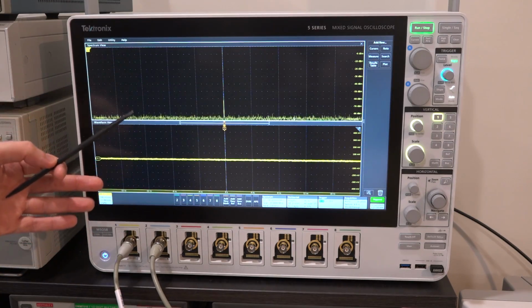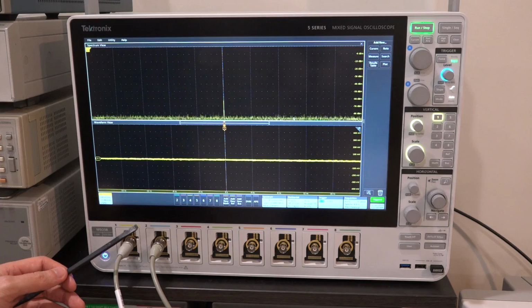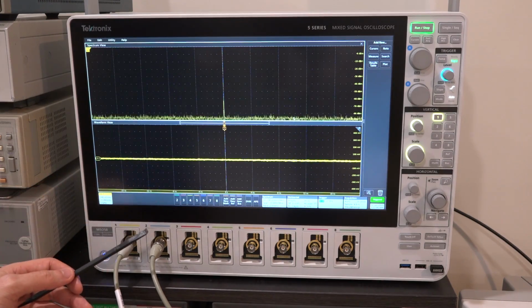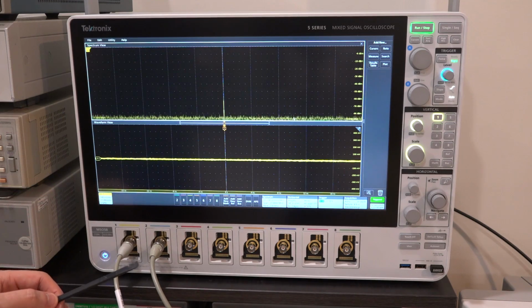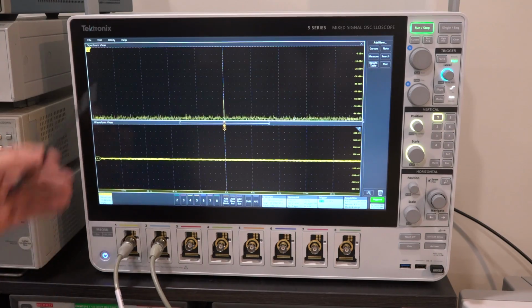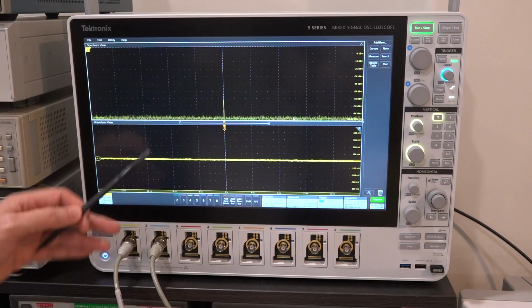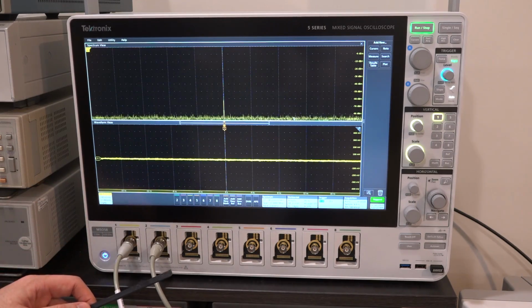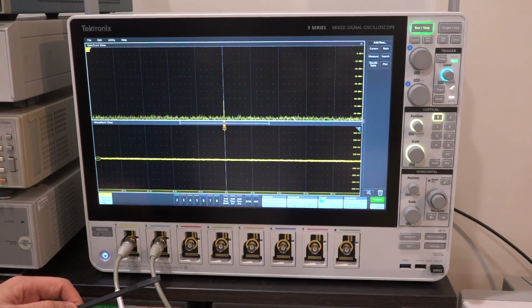Also, very small AM modulation and PM modulation, as I talked about earlier, are indistinguishable in the frequency domain without looking at the phase. And you could do that on the oscilloscope. You'd have to have some software, but carrier removal will have to happen no matter what in order to isolate PM from AM modulation. So there are quite a few reasons. That's why essentially people never use oscilloscopes except for subsampling oscilloscopes, which I've shown in other videos, which can be used for these purposes for other reasons, and they have a very high dynamic range. And when we get into the jitter video, we'll talk about that too.